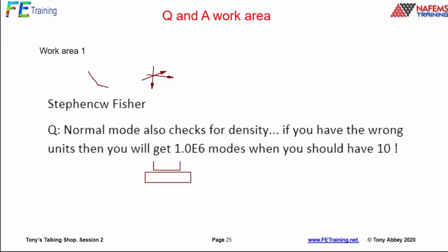So instead of that, I'd say show me the first, say, 20 modes is what I like to go for. Then I've got 20 modes, and you're looking for the frequency value. So that's actually a good point. For my structure, in the same way I've got some sense of deflection level and stress level, maybe I have some idea of what the frequencies are. If it's a bridge, 2 or 3 hertz. If it's a CNC machine, maybe I'm up to 1,000 hertz, and so on. Maybe what you're saying really is, instead of the normal modes analysis, don't worry about the frequency, focus on the mode shape. It's a very good point you make, Stephen. Let's actually look at the frequency there. That could help us.